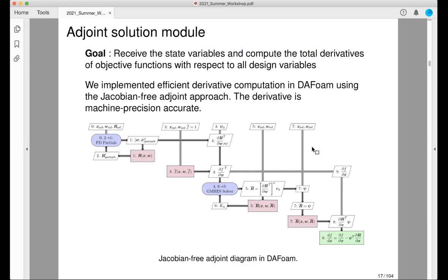So when you perturb the FFD points, we are going to update the surface geometry, the surface mesh. We're going to also update the volume mesh coordinates. So your geometry changes. Then when you recompute the residuals, do not resolve the flow. Instead, just compute the residuals. Your residual will be off, will no longer be 0. Then we take the difference, R perturbed minus R original, divided by delta X. You can compute the partial R, partial X. You don't need to resolve the flow. Does that answer your question?